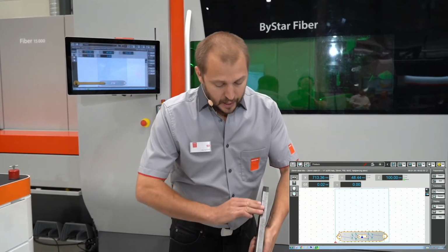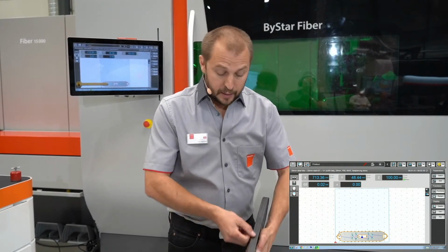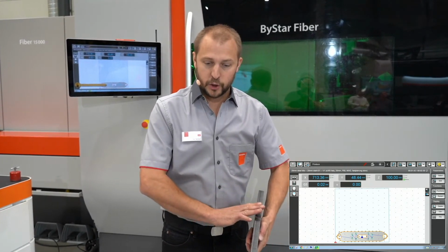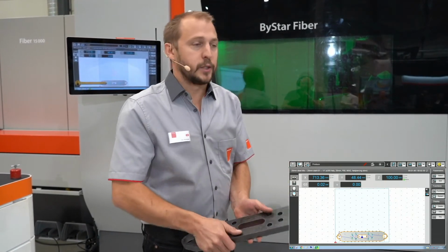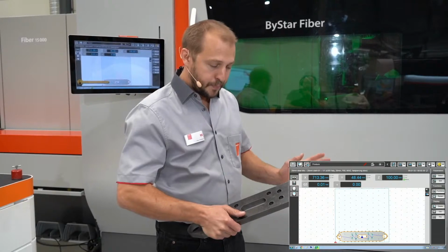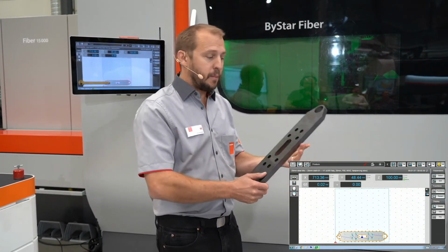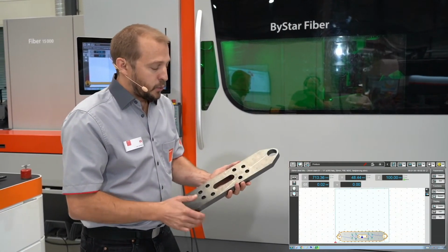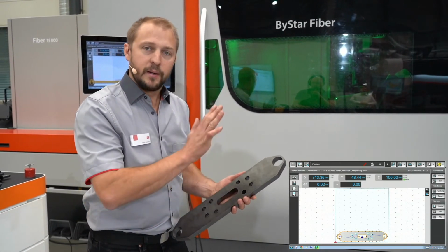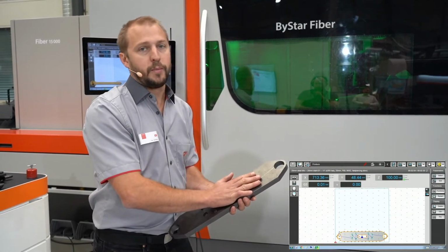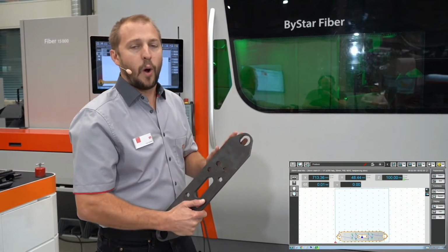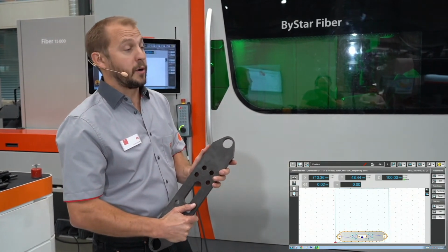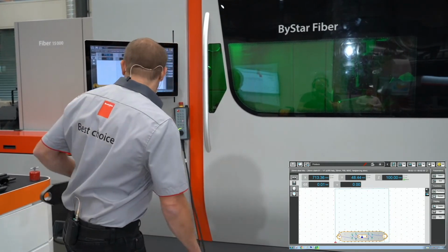You can see, same edge as on the 10 millimeter, it's a little bit oxidized, but we don't need to remove this oxidation. That's the big advantage. Instead, we have a little bit of burr. It's not perfect like with oxygen on the bottom, but weldable and paintable without rework, and much faster. The big advantage as well is we can cut the same part in sandblasted material, in hot rolled material, in rusty material, it doesn't matter. We're always going to get quite a similar result with a similar parameter, and that's a big plus. So let's cut that part.